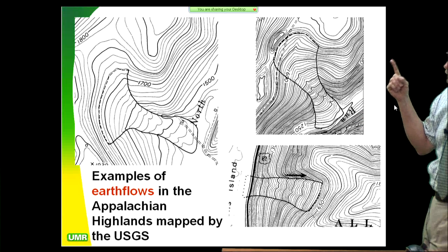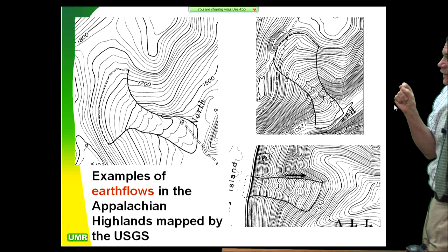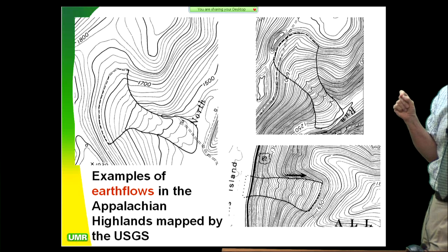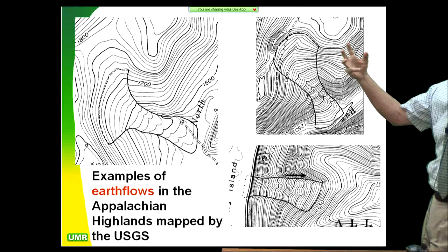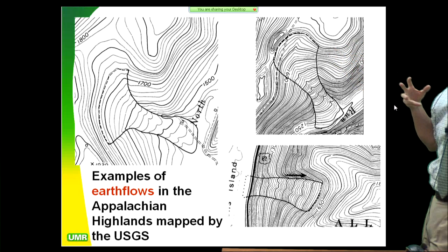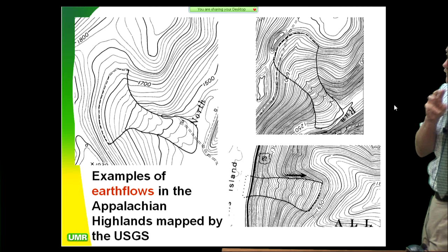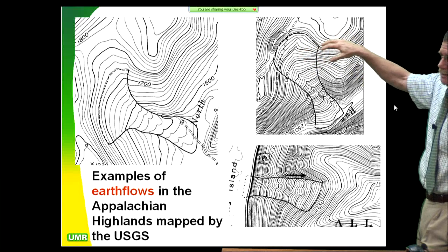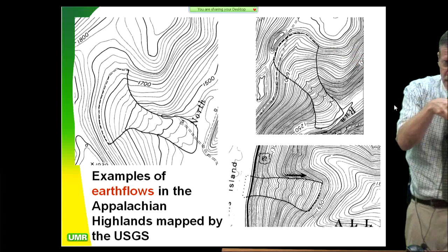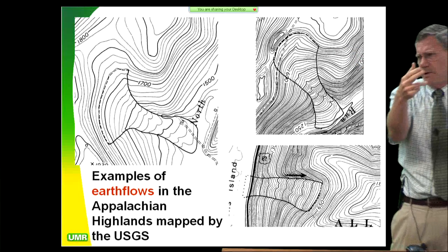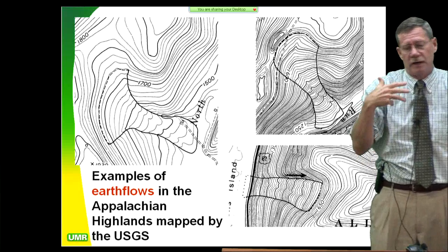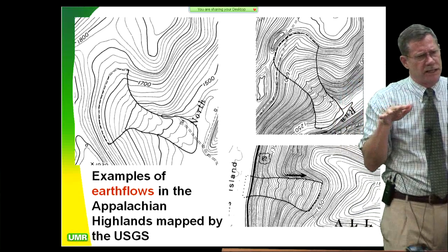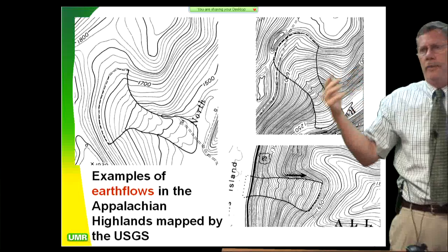One big storm event basically failed every highway culvert in the state because it's a lot of warm moisture coming from the opposite direction of their usual storm flow. If you look at all the record storms on the Appalachian Plateau, on the highlands, they're all from hurricanes coming out of the Gulf of Mexico, coming up through Texas, Oklahoma, Missouri, Arkansas, and coming in from the blind side. The normal storm track on the Appalachian Highlands is coming in directly off the Atlantic. So you're hitting the mountain range from the dry side with a whole bunch of moisture.